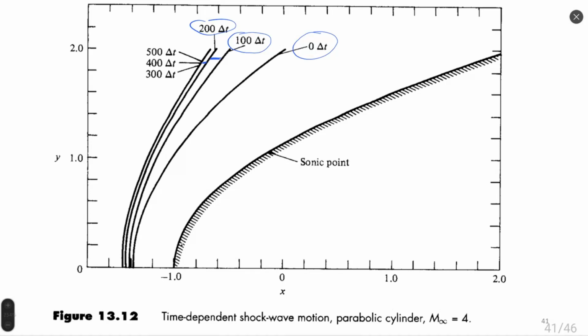Between 300, 400, and 500 steps, we see no difference. It means that we are close to stationary flow and we can finish the calculation according to our stability criteria, stability by mass, momentum, or energy, or any other stability criteria which we can imagine. For example, drag coefficient can also serve as a stability criterion.